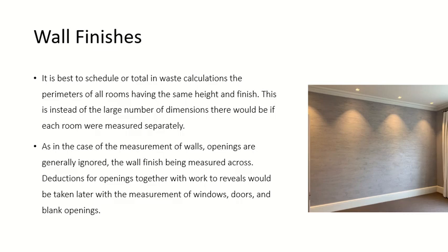For the wall finishes, again you need the girth, the perimeter. So you take the perimeters and you can add the perimeters of the rooms which have the same height and the same finishing, like we did for the walls just now in the example. All internal walls were taken together, because they are made up of the same material. So if you have the same finishes and the same height of the room, you can add all the perimeters together. I have 4 walls in this room, 4 walls in the other room, and 2 rooms on the next floor, but they are the same height and same finish. So I will add the girth of all of them together.